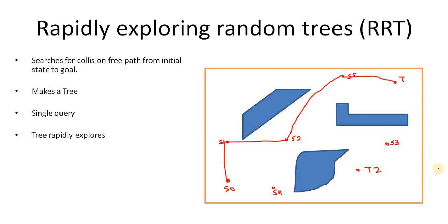Okay, so this is again one of the advantages, because here it says "rapidly exploring." It explores your free space in your configuration space rapidly.